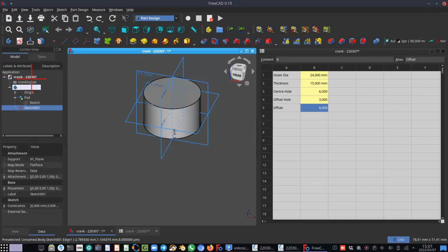We can close our sketch, and what we do now is we click on this icon over here, create a pocket with a selected sketch. Note, we don't click create a hole with a sketch. We click create a pocket with a sketch. Right, holes are used when we use tapped holes or drilled holes, where the drilled hole is a blind hole, and so the tip of your drilled hole is important, the end of it, the bottom end. That's where you use holes or tapped holes.